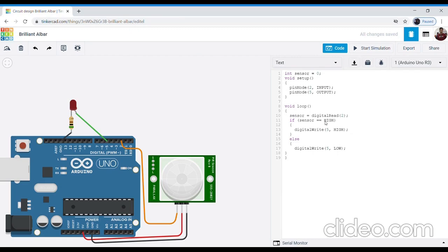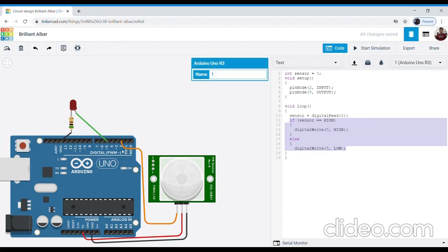So now we are going to learn the if-else statement with an example. If-else is actually a control statement in C language. Instead of looking at it as an output in C, we're going to simulate it with respect to sensors. This is my Arduino. It's got 14 digital pins. These are the different digital pins where you can connect LEDs and sensors.